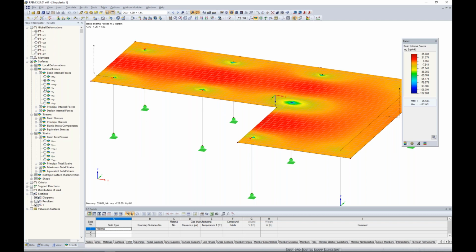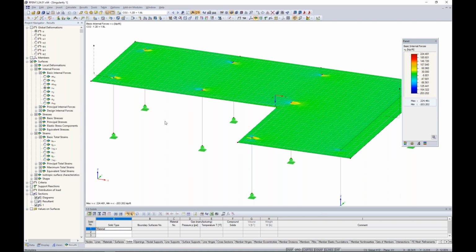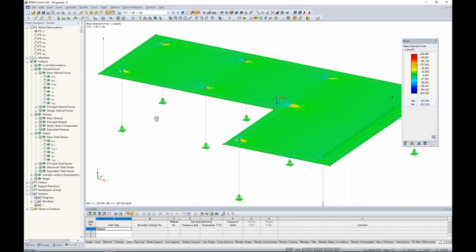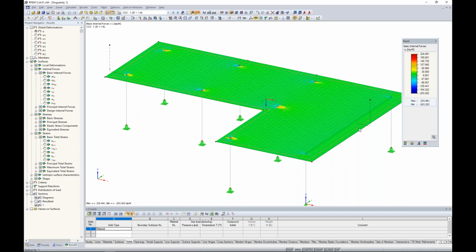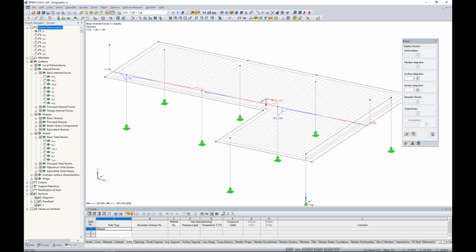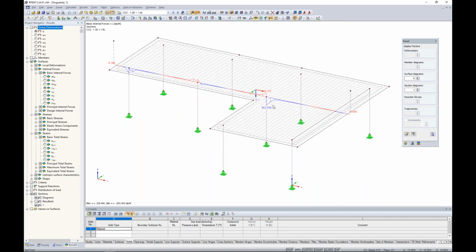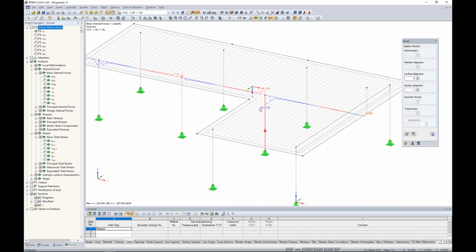And even more so can be said about the shear forces. Now, we fully expect shear forces to be higher at these column locations, but I've also made a section cut through my structure here that I'll go ahead and turn on, and maybe I turn off my ISO bands. If we look at this section cut, you'll see that these shear forces are very high.